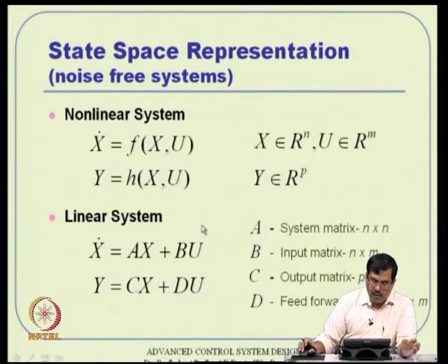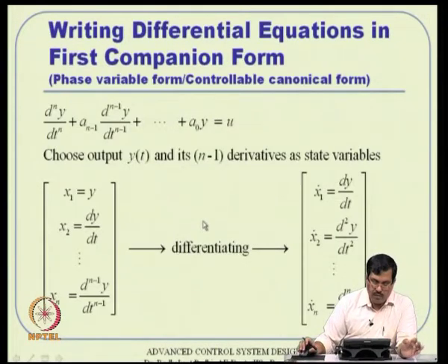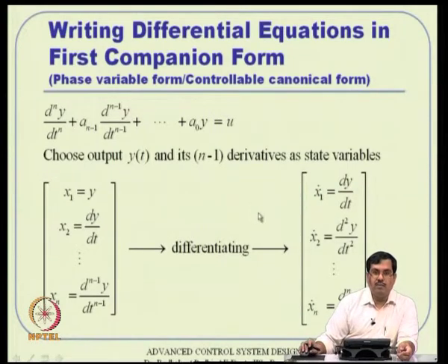Now, we will see exactly how, let us say you start with a differential equation that comes from some sort of physical representation. In other words, for a simple example, you can talk about m x double dot equal to f, right, we know that. So, if you have some nth order representation like that, how do you represent it in a state space form? Very frequently we will come back to that question again. Okay, so let us see how to do that.